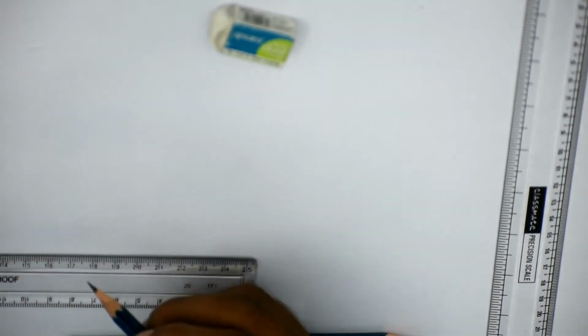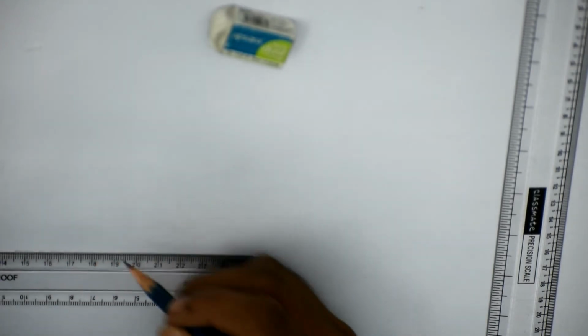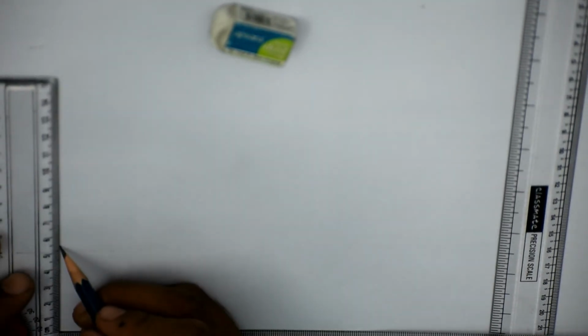So as I have mentioned that in this case the cylinder is inclined to the horizontal plane, but we need to assume that it is resting on the horizontal plane first, and we need to draw its projection. Then we can start our actual diagram. So for that to happen, as I have assumed that the cylinder is resting on the horizontal plane, this will become very similar to our first question. That means cylinder is resting on the horizontal plane. So the top view will be circle.